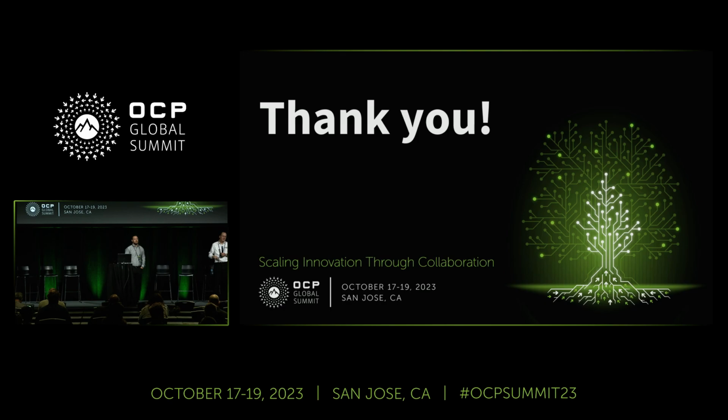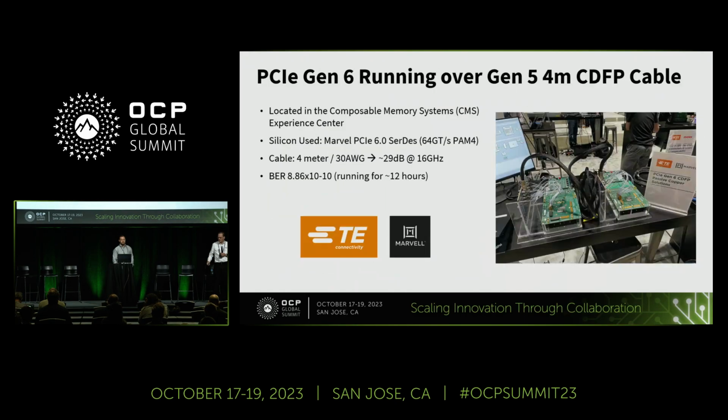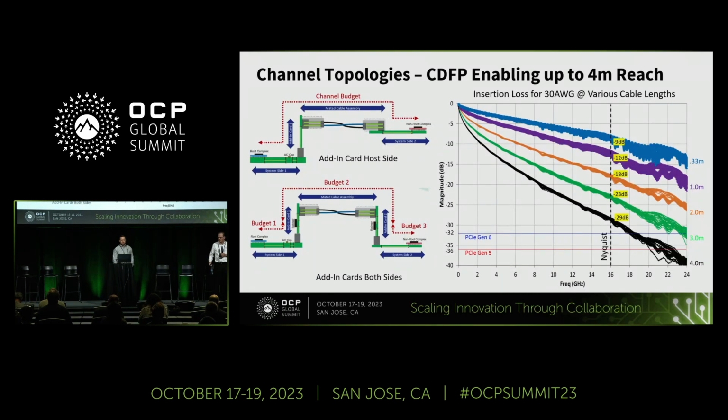No, on the other end, where you showed the connector and the retimer on a card vertically. So you have the additional, like on that lower solution. Yeah, so we're showing, in this case, retimers on both ends. So that's additional 8 dB loss for the retimer on both ends, right?